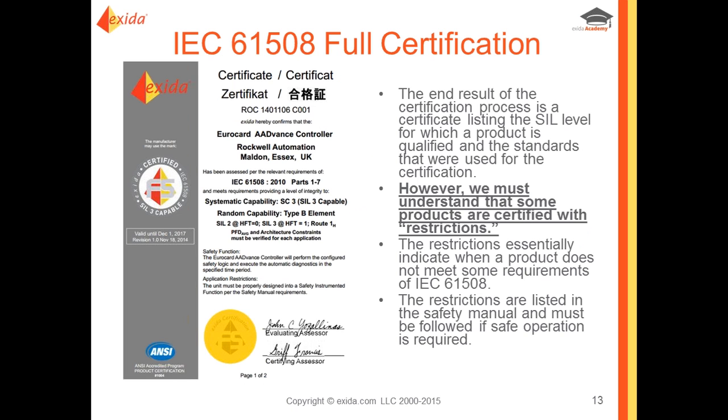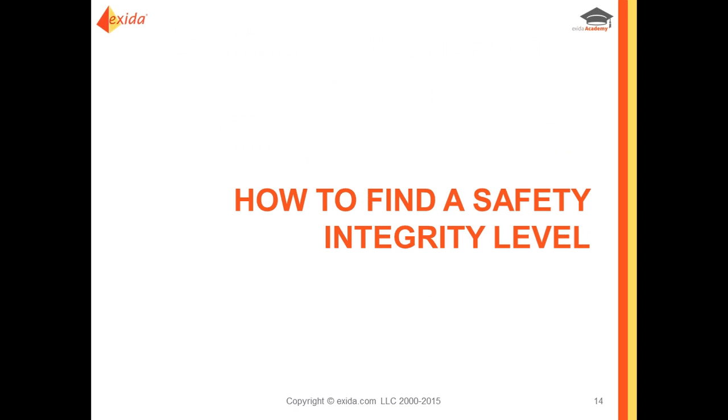Next, we perform FMEDA analysis on the product. We take apart each product and break it down per component to find out each way each part can break, and give you both your dangerous failure rate and your safe failure rates from it.